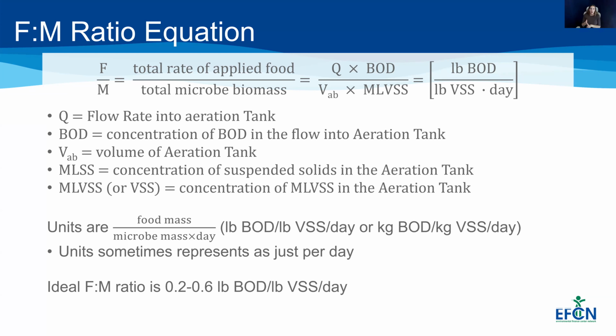And this could be pounds of BOD per day, or pounds of BOD per pounds of VSS per day, or kilograms of BOD per kilogram of VSS per day. And that VSS is just the volatile suspended solids. It's similar, it's taken from that MLVSS. Also, these units may be represented as just per day because you cancel out the pounds.